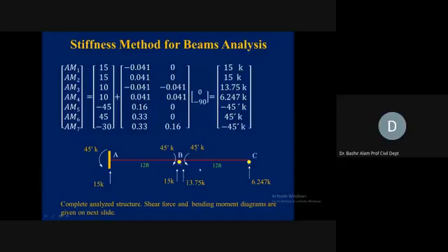At the AM3 location, we have then AM4, and exactly now you can see this was our AS3, 15 kip, and this was AS2. Exactly, we have the same numbers, and if you add them up, 28.75, again we have the same reaction from these values also. AM5 is minus 45. Our assumed direction was clockwise, so we reversed the direction because of this negative, and we put this on the sketch now.